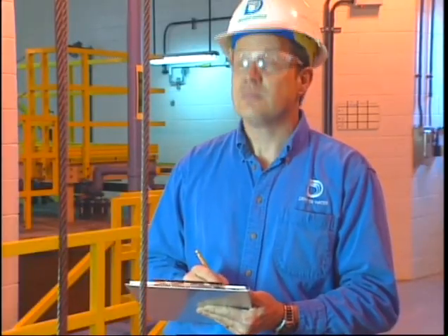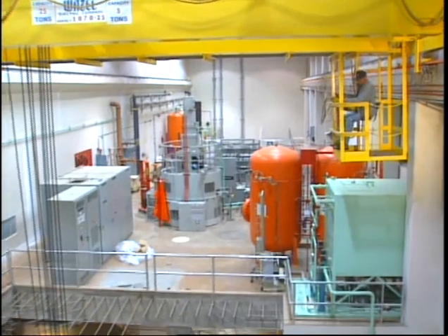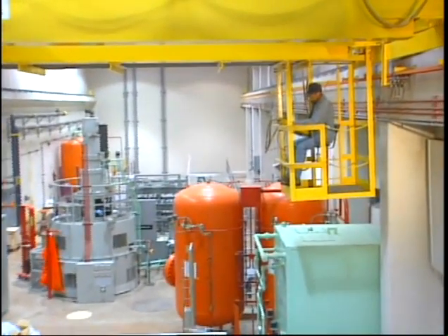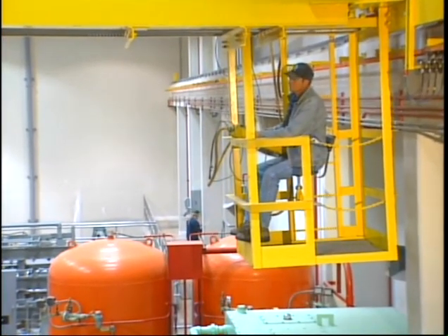And finally, if the machinery has been disassembled for maintenance and repairs, the inspector should conduct load testing to make sure the hoist is operating at its designed rating. The inspector's periodic written record should be filed along with maintenance records for the machine.